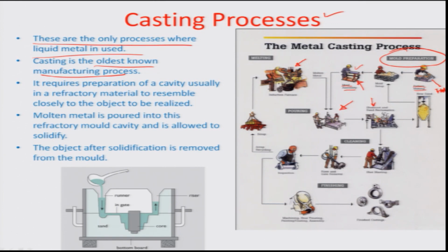And what comes out is basically a component where you have to clean the component. So you have to sort of trim off the component. Let us see this figure for example. In this figure you are pouring the molten material through a ladle into this section which is the runner, and it goes all the way into this particular part, where the part is again filled with some kind of a core. The core is normally used if you want to create a hollow casting.